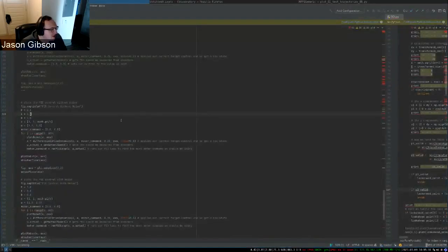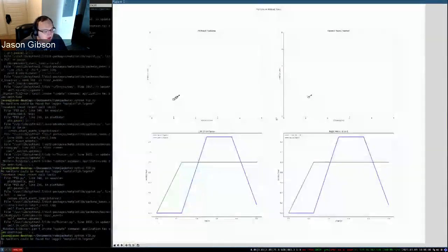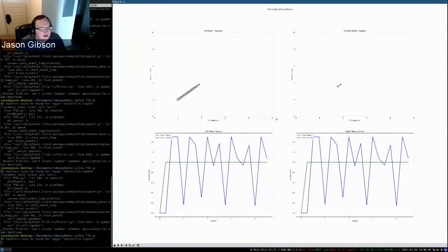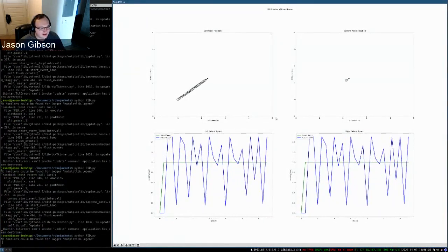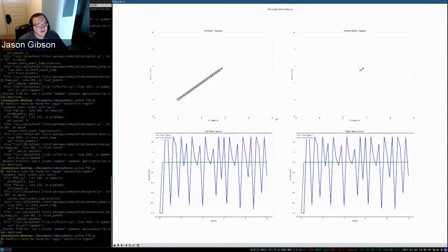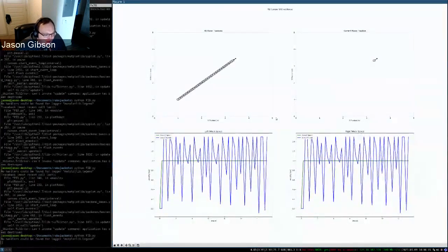Let me show you what it looks like if I make I too large. This is the thing Varun was talking about earlier when your I is just way too large. You can see how we're having the same behavior as P, but it looks slightly different. It's not just directly oscillating. It has some lunges as it goes through. So this is how you know that your I is too large.